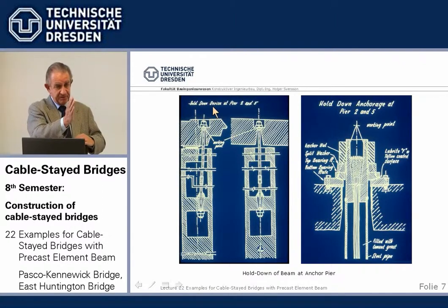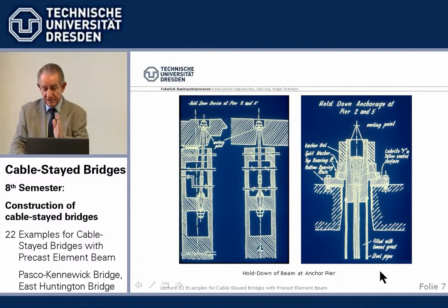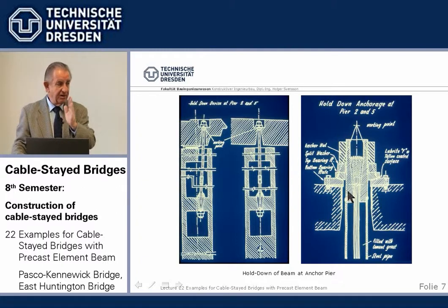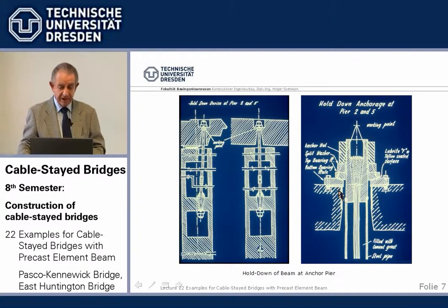So we must prevent that there is a kink in the cable, and therefore we have used stiff steel pipes here, and we have placed the bearing on a sliding surface, and so it's forced by the strong steel pipes and the sliding here that we always have a rectangle between the hold-down and the anchor head, and there is no sharp kink, which could cause breaking.